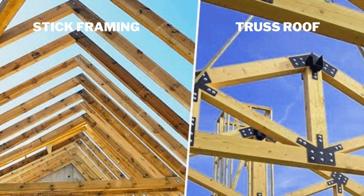Step number 13 is truss design or engineered roof. If you are going with stick roof framing, then your architect will design it and your contractor is going to build it. In that case, you don't have to deal with a truss agency. But if the building span is large, then you need a truss roof. For that, you must send drawings to the truss agency and then they will provide you the detail with an engineered stamp. You must submit those drawings to the municipality with the permit drawings.